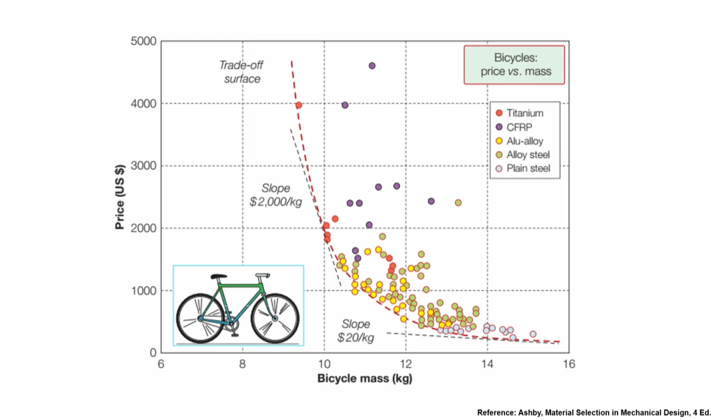We use this concept of the exchange constant E, keeping the cost as -1, and then you can do this problem graphically, and you can see that in case of a bicycle, if the mass of the bicycle is not your concern, then the exchange constant becomes something which is pretty low at a higher value of mass, which means if you are going for a heavy bicycle, okay, not a high end, a low end, then you do not have to think much about the lightness of it, because the exchange constant is only $20 per kg. Whereas, if you are going for the high end, okay, then the slope is much sharper. So, every single gram there, okay, is very, very important in terms of the exchange constant.